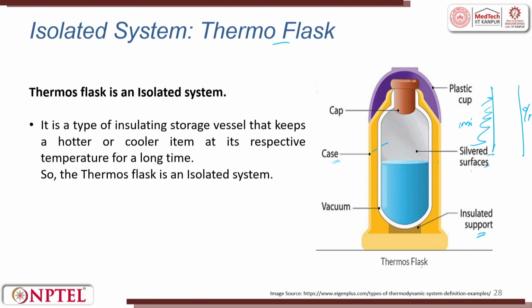So, this is a complete isolated system. There is no mass transfer, there is no energy transfer. It is a type of insulating storage vessel that keeps hotter or colder items at their respective temperatures for a longer time. So, it is an isolated system. If you keep the lid open, this lid and this lid open, then it becomes an open loop system. So, think about it. Can you make it a closed loop system?